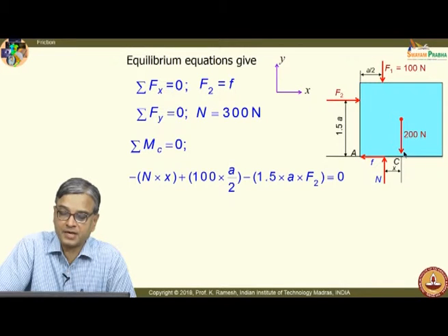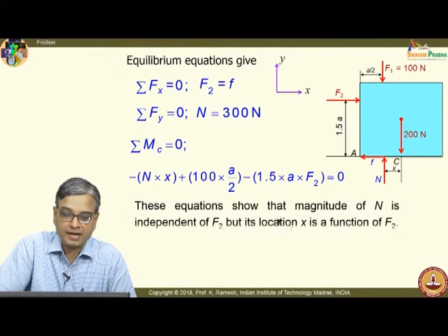This force, since it passes through C, does not contribute to the moment. All the forces are accommodated. On simplification, I get an expression for the distance x.